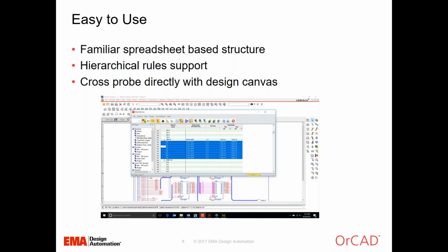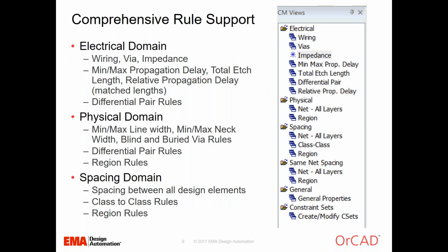EMA's new CM for OrCAD provides you with a familiar spreadsheet-driven user interface that is so similar to the PCB Editor Constraint Manager that no additional training is needed. As in PCB Editor, constraints are contained within a hierarchical structure. Constraints that you specify at the top of the object hierarchy are inherited by the lower-level objects in that hierarchy. Constraints that you define at the lower levels of the object hierarchy take precedence over or override constraints defined at the higher levels of the object hierarchy.